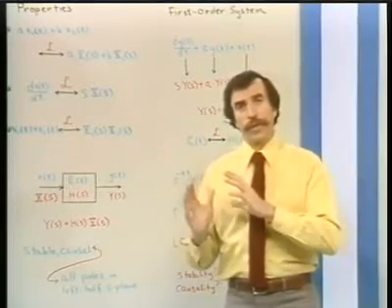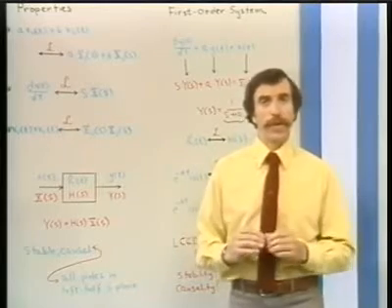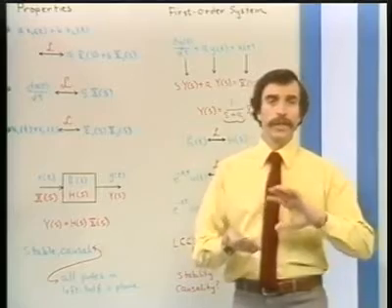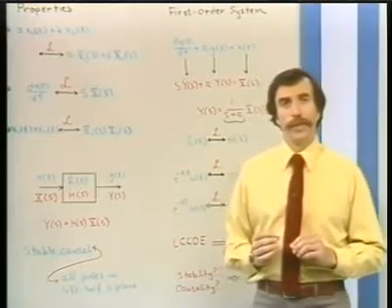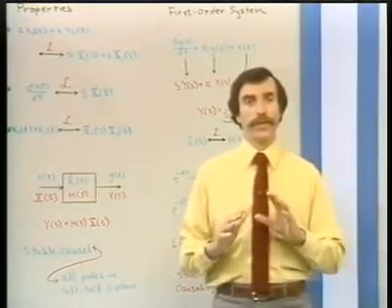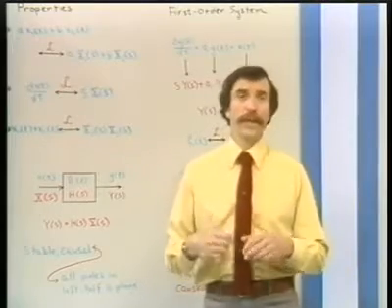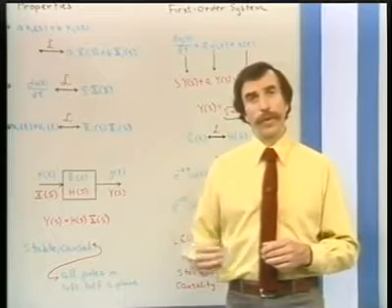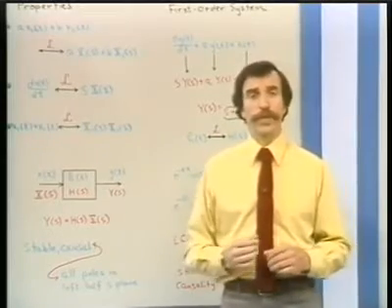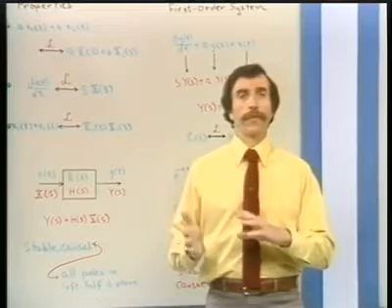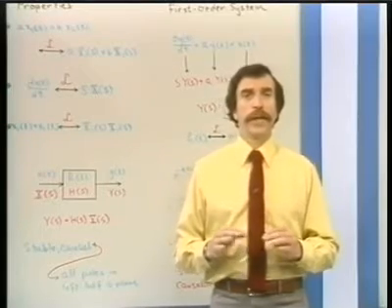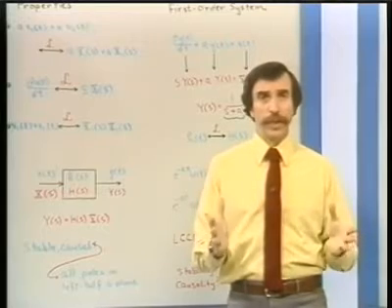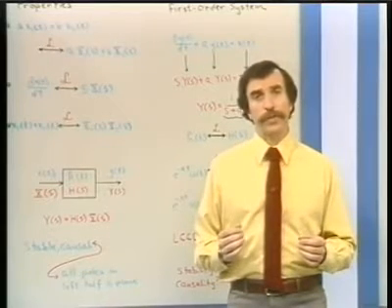some issues of the region of convergence, and for that matter, location of poles of the system function, are closely tied in and related to issues of whether the system is stable and causal. And in fact, there are some useful statements that can be made that play an important role throughout the further discussion. For example, we know from previous discussions that there's a condition for stability of a system, which is absolute integrability of the impulse response.